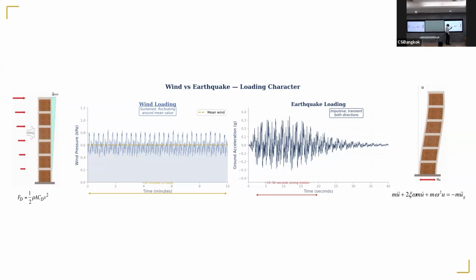So in ground motion, we apply just one ground motion for the entire structure, but for the wind, we may be applying like 100 time histories simultaneously, because the pressure is varying at every location and direction. So it becomes very complicated.